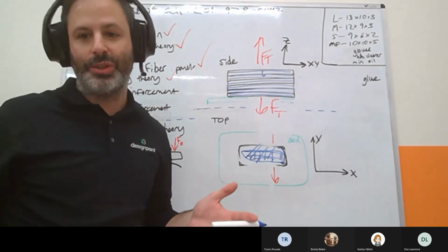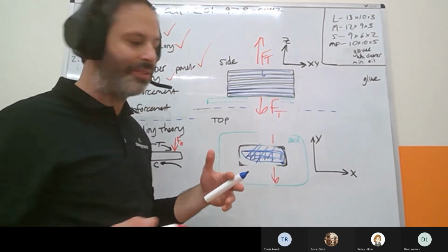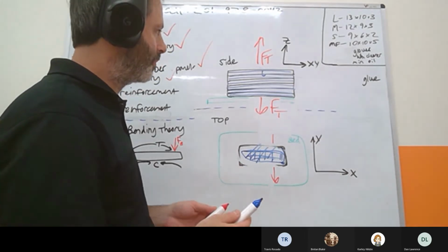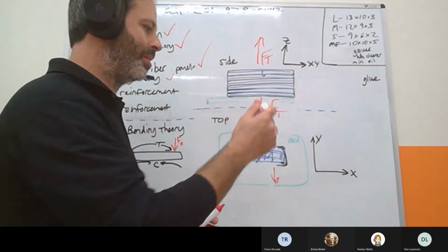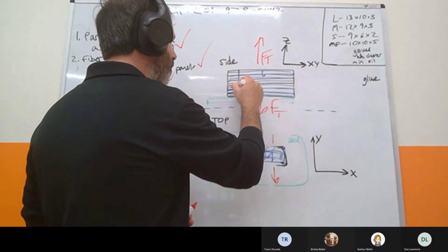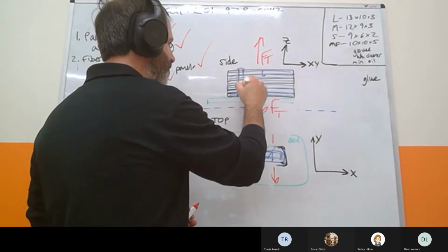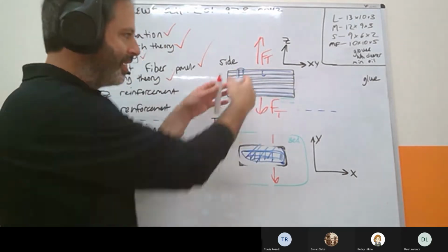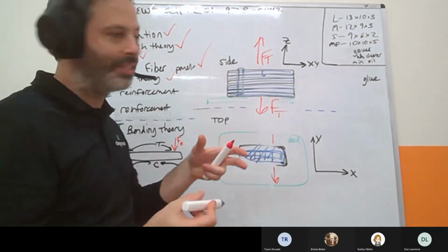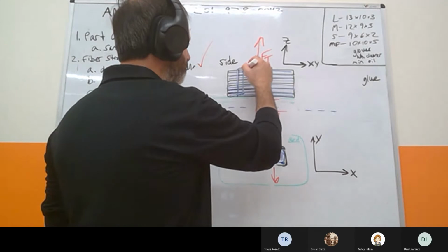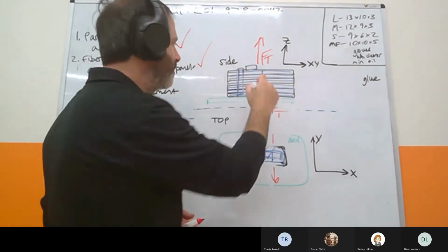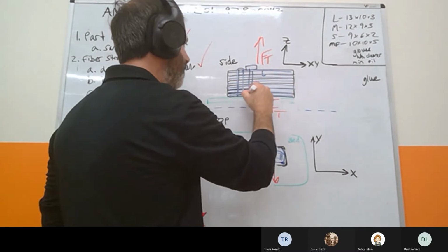What you could do in this situation, some other strategies not involving fiber, are, if you're scared of some sort of shear failure coming in, you can print a hole and put a dowel pin through. Or in this exact scenario where you're really trying to reinforce for this tensile load, you could print holes through the part and put a couple bolts through.